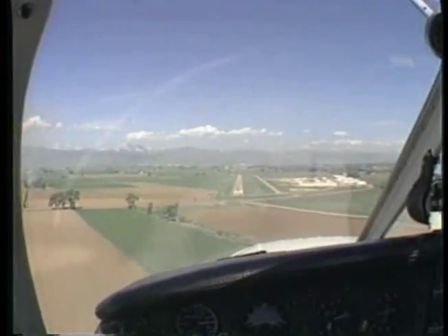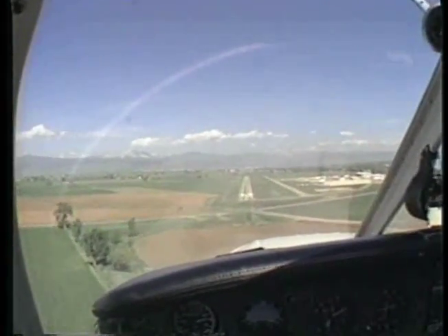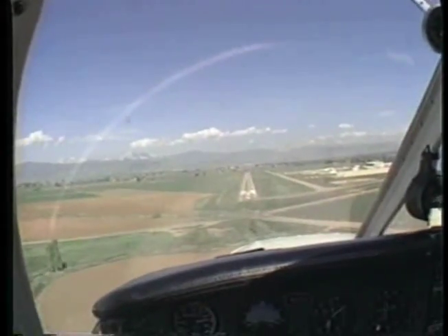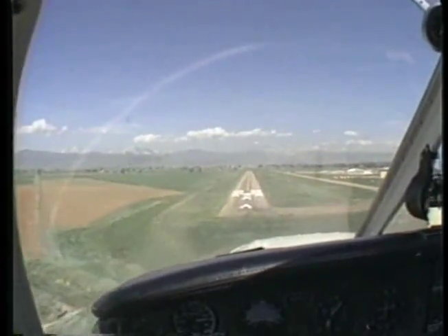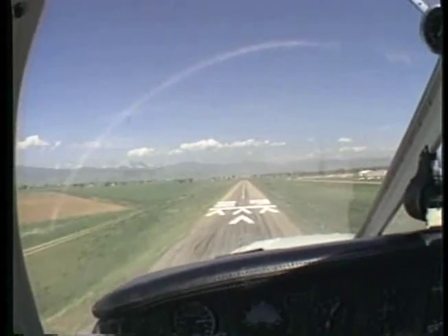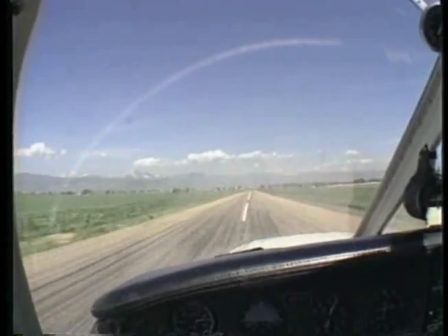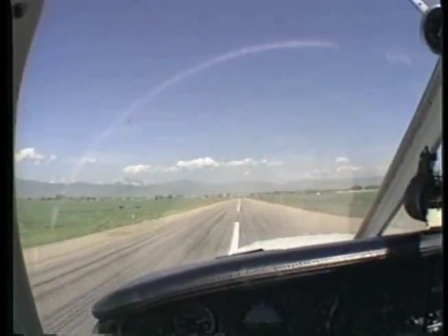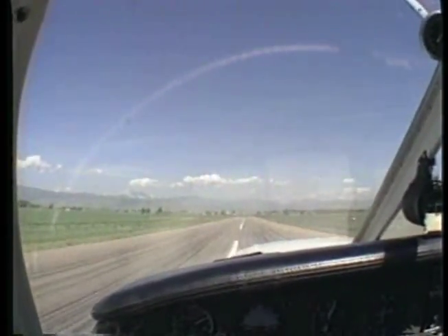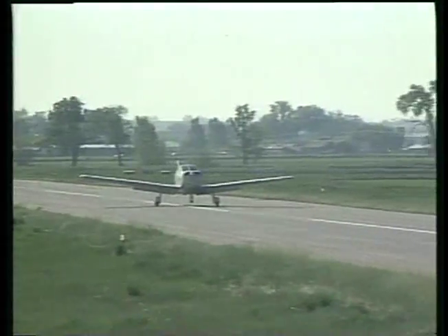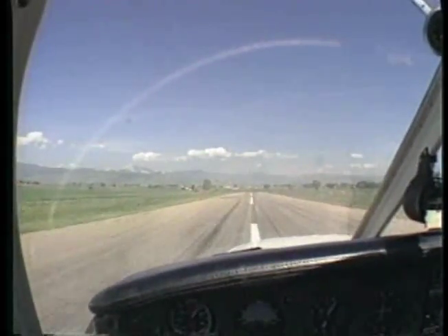The flare and touchdown require precise pitch and power control. If runway length is not a problem, you might want to carry a small amount of power during the flare out. Then, as you near the surface, smoothly raise the nose of the airplane to an attitude which resembles the climb attitude. In this way, the airplane will settle onto the ground as gently as possible. Maintain this power and elevator back pressure during the rollout to help keep the nose wheel off the ground as the airplane decelerates. Deceleration on a soft surface is generally quite rapid. Therefore, braking, other than that required for directional control, is usually not needed.